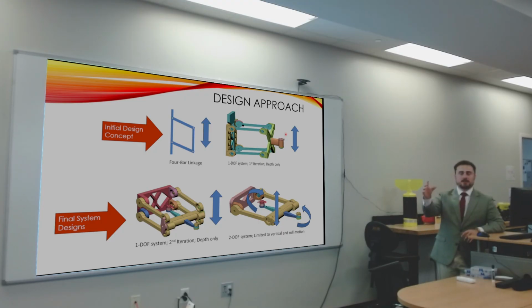So whenever you become neutrally buoyant, your system rises up, and then the microcontroller says, okay, we're approaching the goal, let me decrease the strength of the motors. As it gets to within a certain tolerance of the goal, the motor turns off, and then it falls again. Or if it's too strong, it blows past it, and so it keeps a constant set of oscillations.